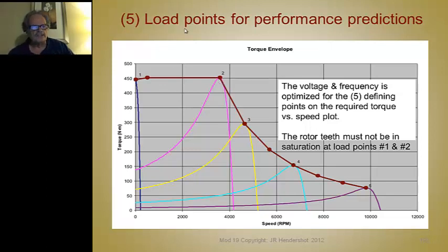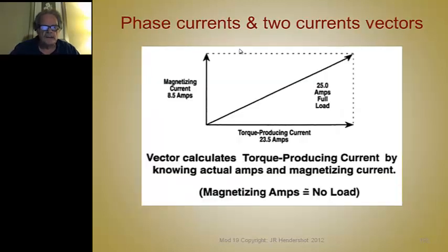But you could also use the same analysis and determine a peak constant torque and constant power range that maybe could operate for 10 seconds or 20 seconds or a minute or 2 minutes, used for accelerating the car or going up a grade. And that's a requirement too, so you can use the same process to identify that envelope.